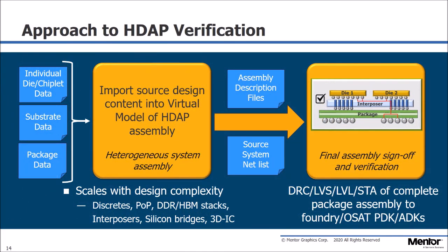This is the data flow for Mentor's HDAP solution that comprises Xpedition Substrate Integrator and Calibre 3D Stack. The individual source design elements are integrated and assembled as a heterogeneous system within Xpedition Substrate Integrator. This model is then directly driven into Calibre 3D Stack, where DRC and complete package assembly verification can be conducted using assembly design kits or process design kits provided by the manufacturing foundry or OSAT.